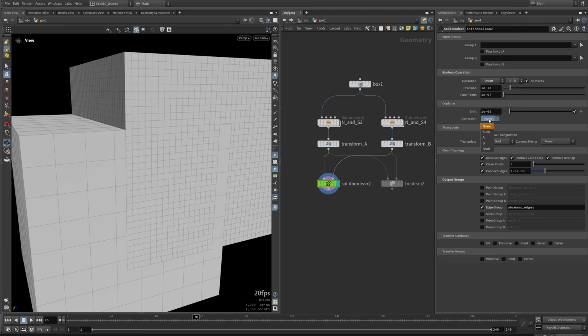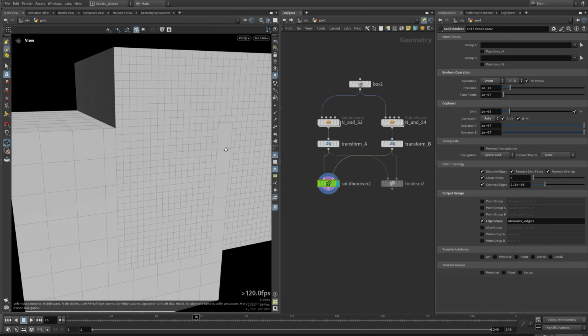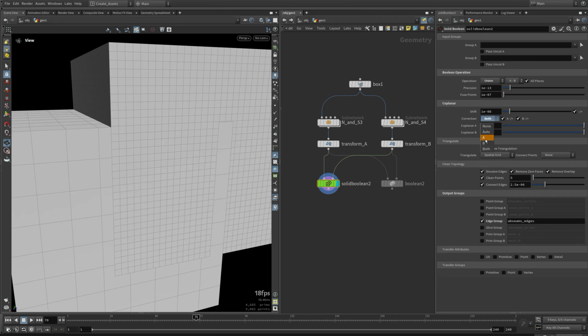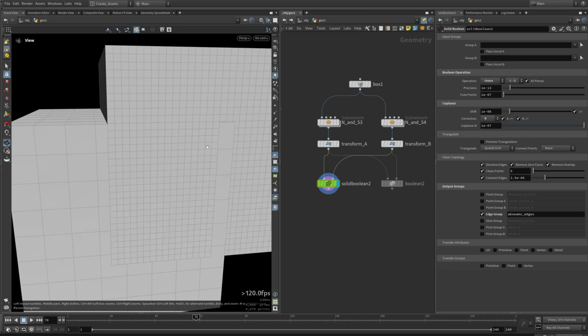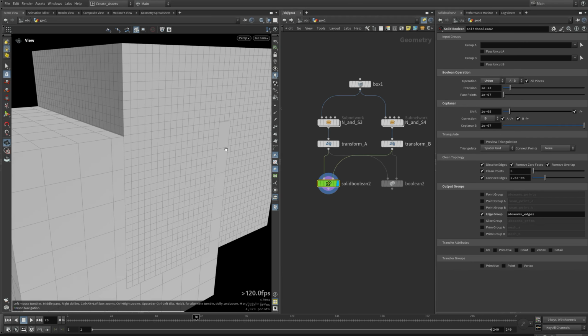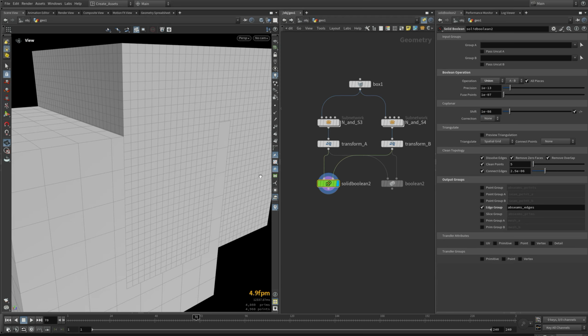There's also a correction parameter that physically shifts the points to eliminate floating point noise when surfaces are very slightly offset from each other. However, this parameter can slow down the Boolean computation. It's a temporary feature that I decided to keep for now, but it will likely be removed in future versions because it's redundant, especially since the shift parameter already does its job perfectly without physically altering the geometry shape.